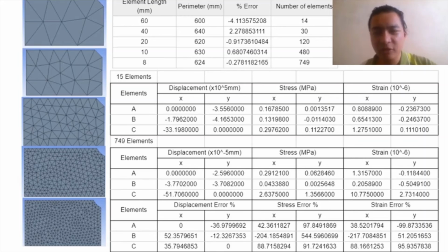Since the software utilizes the length of the element to draw the model, the closer the approximation is to the actual parameter, the better the constant strain triangles are able to represent the actual structure. An error of 0.5% from the actual parameter would be the optimum number, as theoretically, further increase in elements will only bring little and diminishing improvement in the final answer.